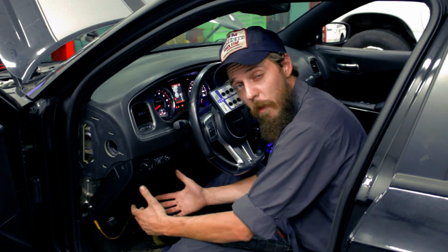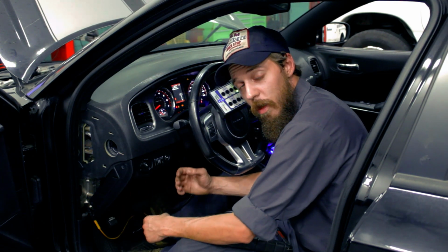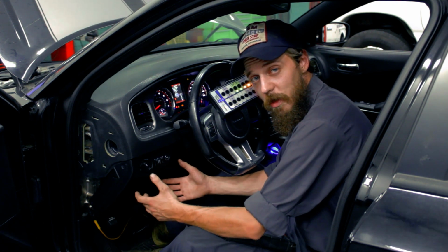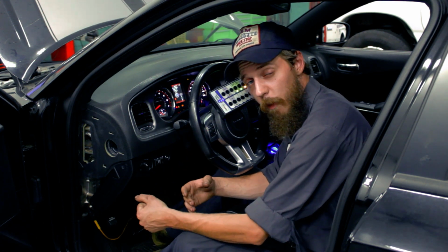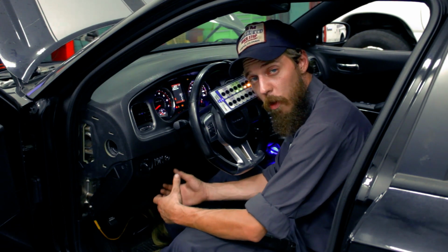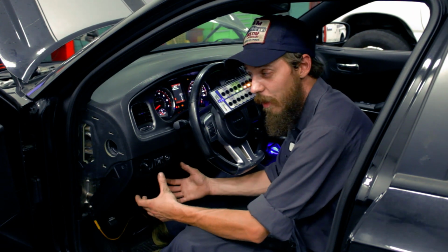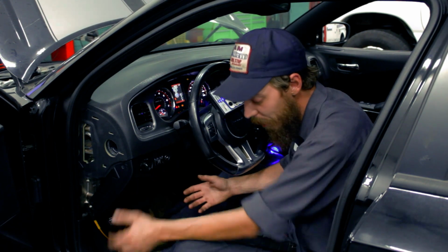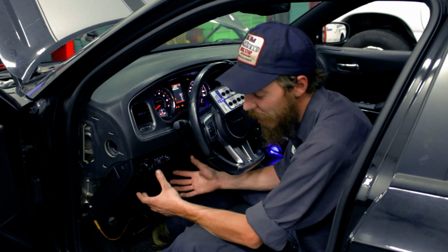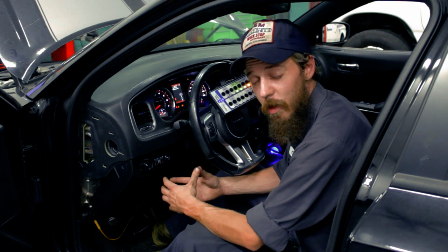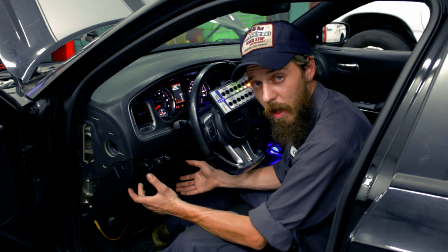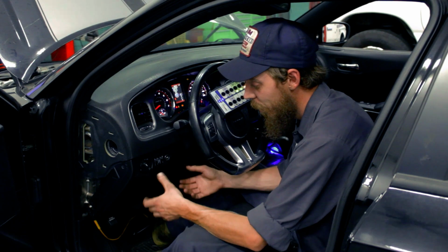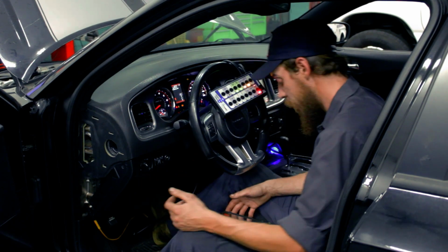Well, we're going to pull up the schematic, and we're going to take a look, see where the easiest place to get to that temperature sensor wire is. We know we're reading a lower voltage than what we desire to read in park or neutral. Now, 99% of what I do is in a flat bay. I don't work off of a lift. A low-to-the-ground car like this means it's not easy for me to get directly to the transmission plug and test it there. So I'm going to look for what's the easiest access point.